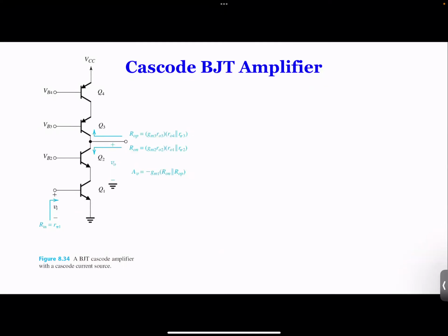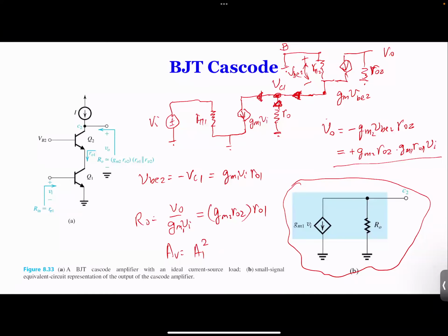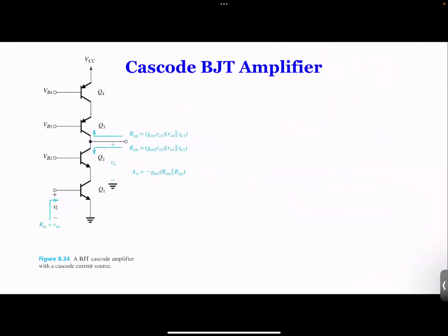But you might already think, what happens if that current source is not ideal? That goes back to the three transistor case as a MOSFET. Then the gain will be much smaller because RO3 is going to be that, right? So ideally, we want to simulate what we can do with multiple transistors with the PMOS at the top as a load device.